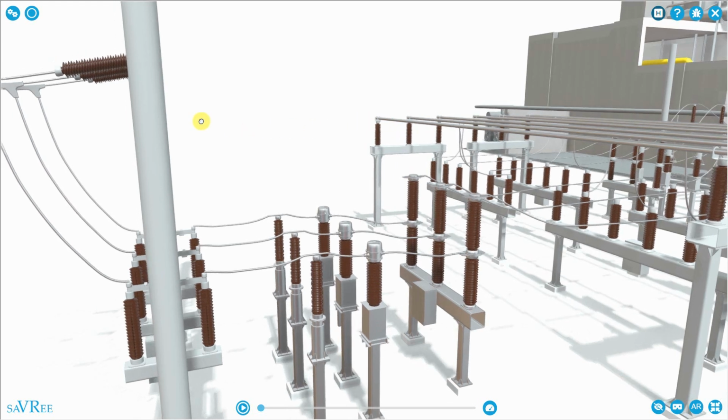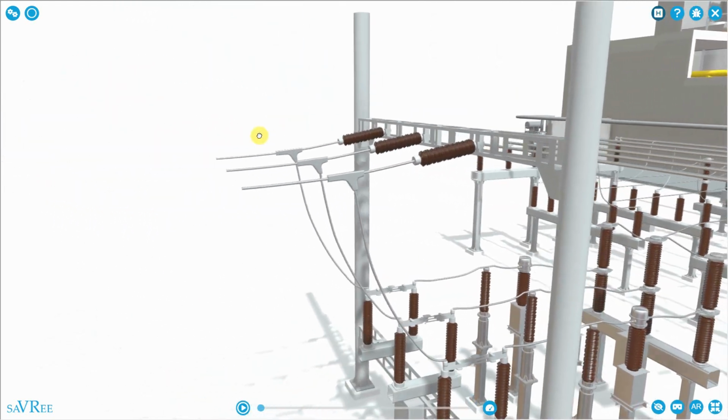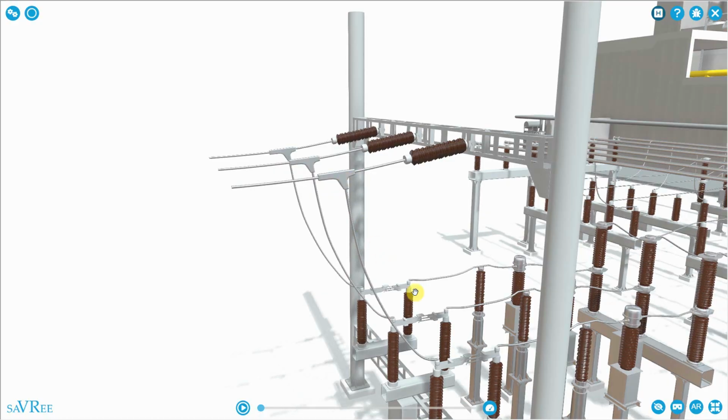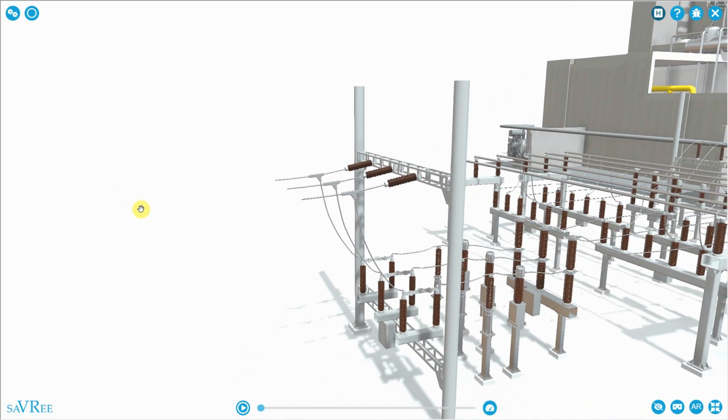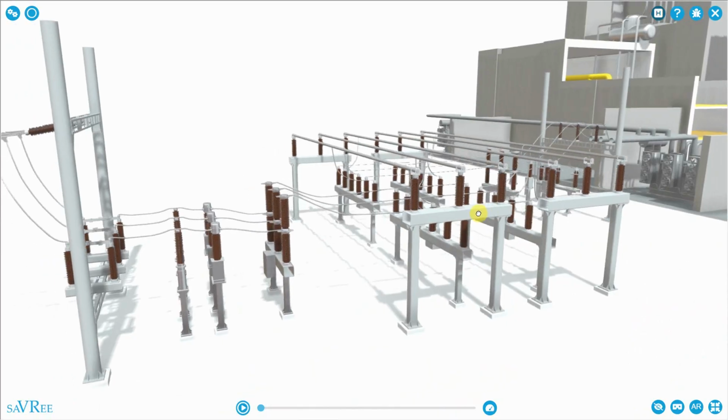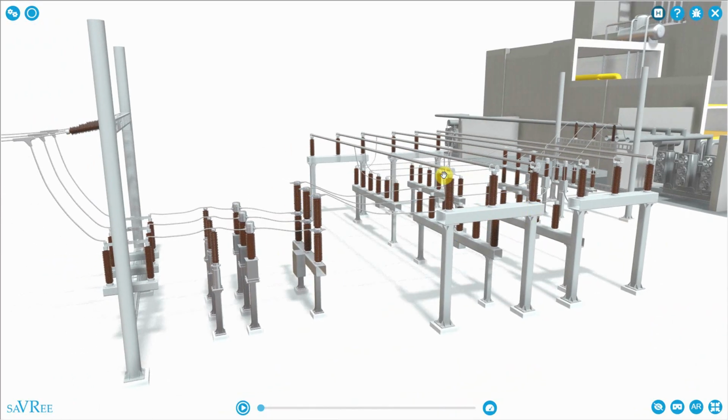Once the electrical power has passed through the open air switchyard, it comes to these connections here and feeds upwards, and then it will go to a transmission tower, also known as a power tower, and that represents our national grid. The voltage within this open air switchyard is going to be perhaps 110,000 volts, 220,000 volts, maybe even higher, up to about 380,000 volts.